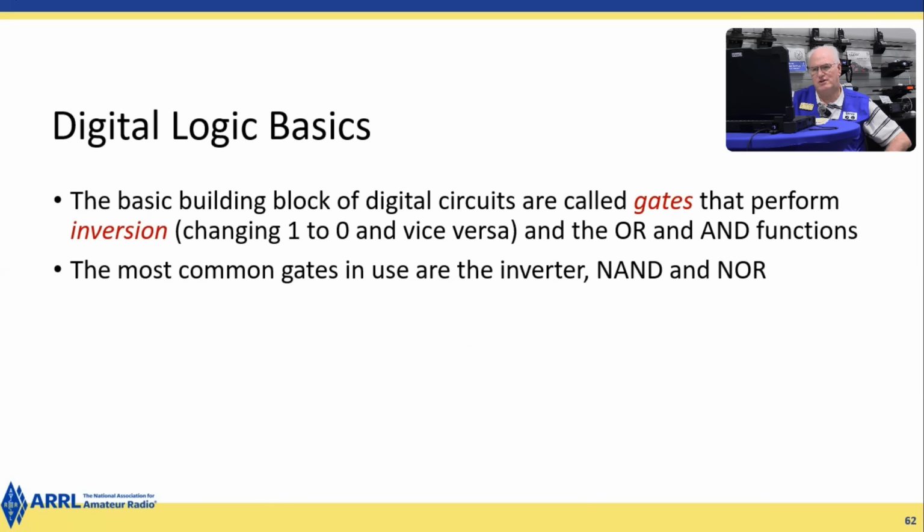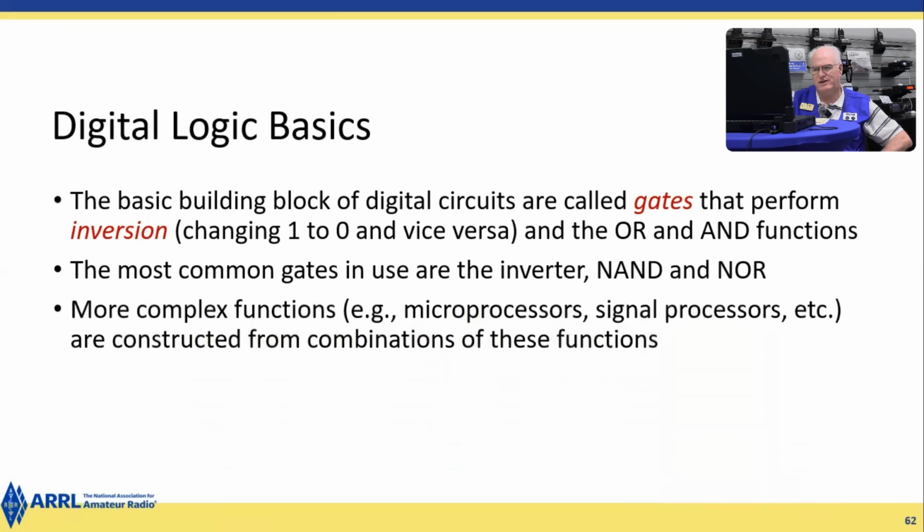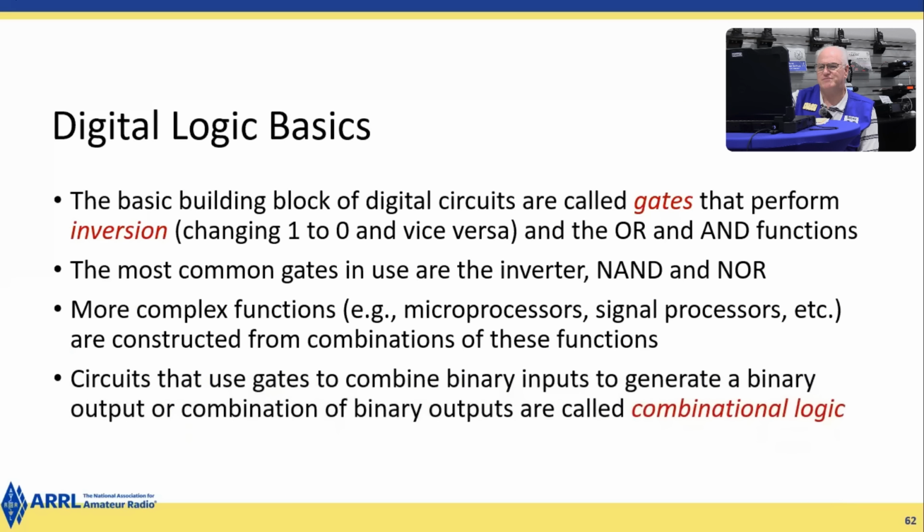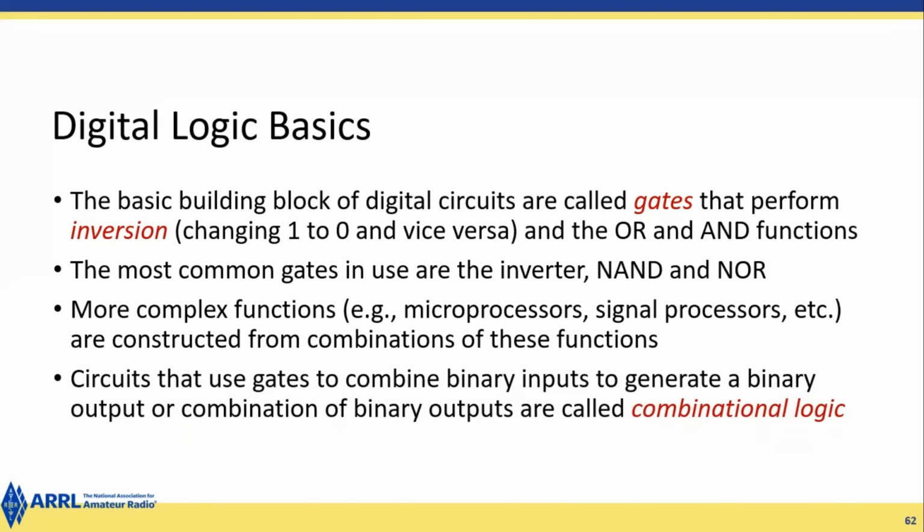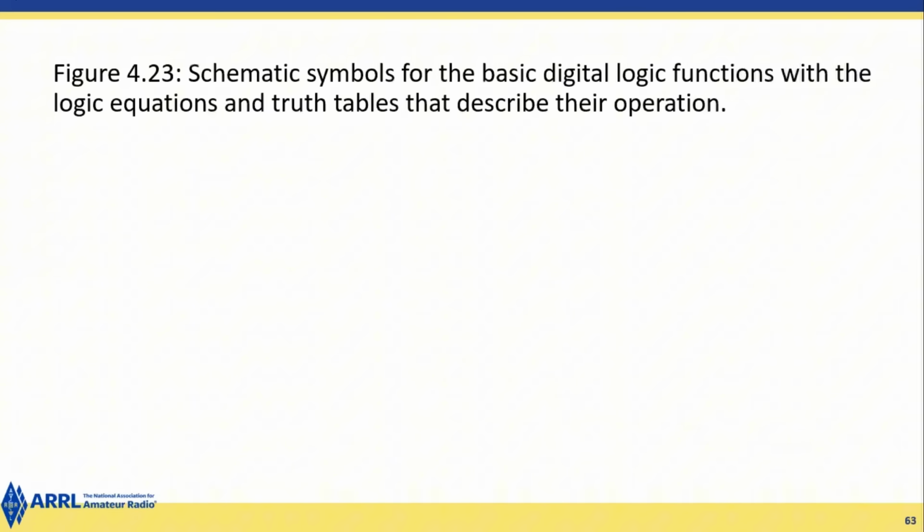The most common gates in use are the inverter, NAND, and NOR. For more complex functions, such as microprocessors and signal processors, they're constructed from combinations of these functions. So all the inverter, NAND, and NOR are the basic building blocks for all the big microprocessors that we have. It's just a whole bunch of combinations of those gates. Circuits that use gates to combine binary inputs to generate a binary output, or combination of binary outputs, are called combinational logic.